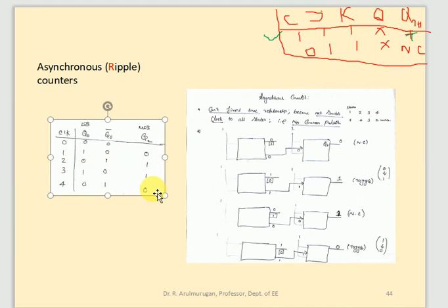Coming now to the first flip-flop place. What is the previous value? 0. See here, this previous value I have written. Then here the clock is 1 and JK also 1. The answer is toggle only. So 0 is replaced into the 1. That 1 I will count as reference. Then 1 is replaced into the 0. Then that 0 I have written here. 0 toggles to 1 and 1 is reference. 1 toggles to 0. So that's why I have written in that bracket: 1 0 1 0. That is Q naught. First flip-flop, sorry, Q naught value, not a bar. Q naught value. Okay.